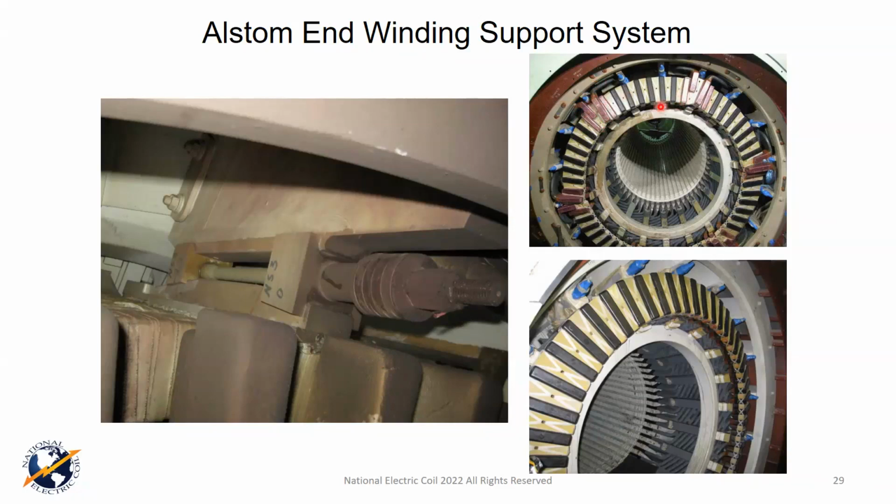And this is after a rewind that we did, so you can't see the exact configuration in this picture. But when we talked to the customer, we were doing it right in front of the OEM, and we expressed to them, "Hey, we really think there's a resonant condition," and the OEM told us we were full of cow hooey. And we told the customer, "Look, the first thing we're going to do, if you want to work with us, is we're going to go in and bump test all these other phase rings to see what's going on." Make a long story short, they gave us the job.